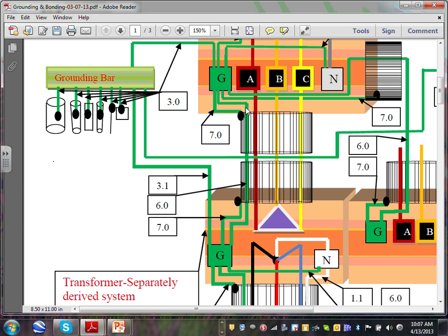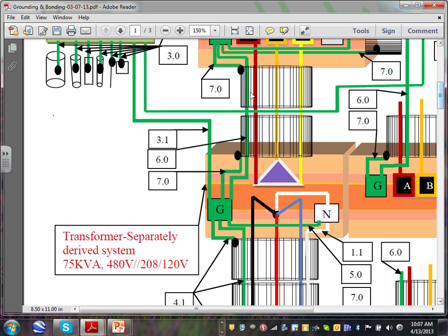So going to this side, this is where number 7 is. Can you see that number? I have it here as number 7, and number 7 here. That's the equipment bonding jumper, load side, and number 6 is the equipment ground conductor. It could be one wire that does both functions. It can't be a conduit though, because you don't want a conduit connected directly to it, unless you come from the bottom, like I said. So 7 and 6 here could be one wire.